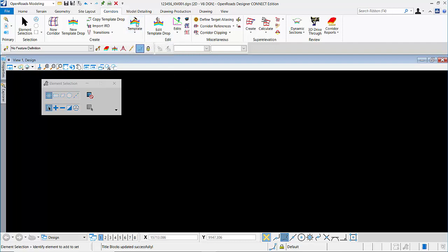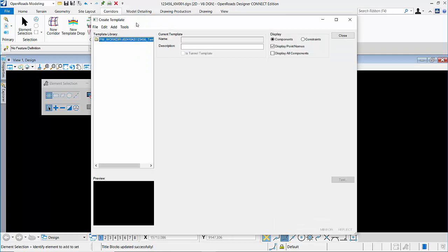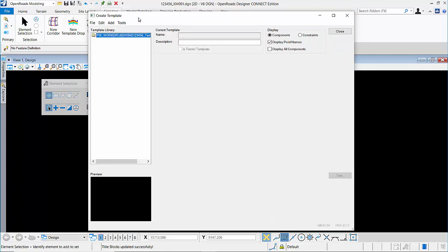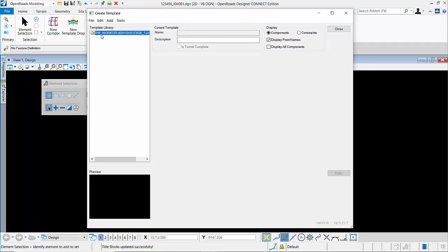And this is going to open the template library that's stored in the 990 Workset Standards folder for our particular project. So if I expand the template library folder here, we've got the ODOT group and the Project Templates group. So I'm going to right click on Project Templates and I'm going to create a new folder. I'm going to name this folder St. Peter Road. And we'll create all of our templates for St. Peter Road within that folder.